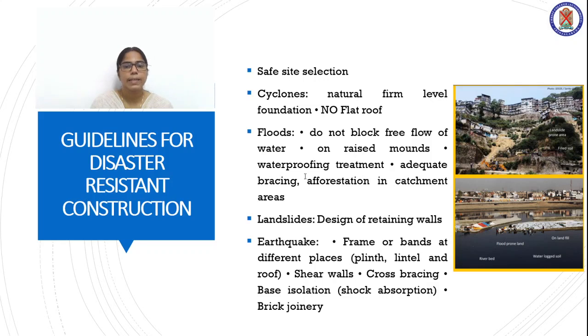The building as a whole should be kept almost symmetrical. Simple rectangular shapes behave better in an earthquake than shapes with multiple projections. And separation of a large building into several blocks is required for symmetry and rectangularity of each block.